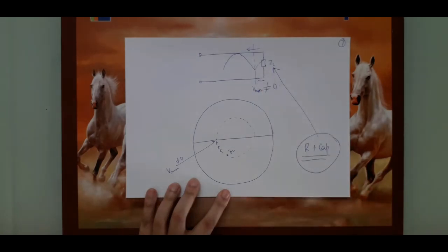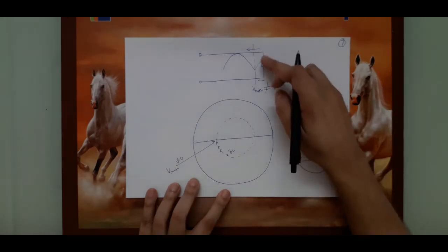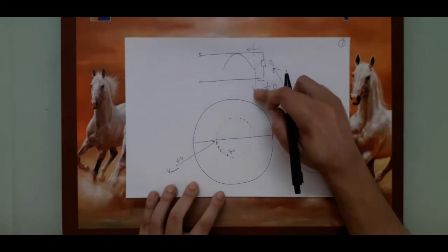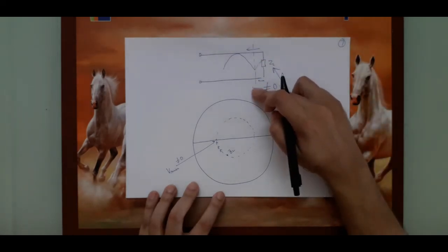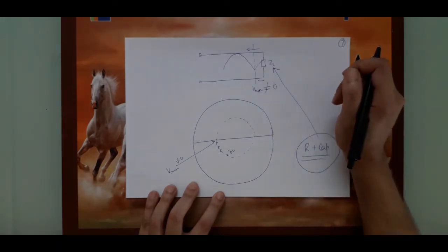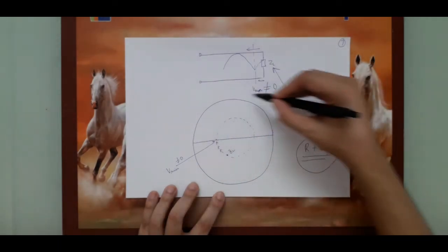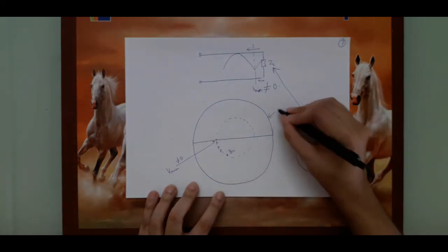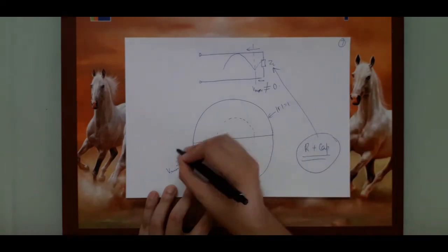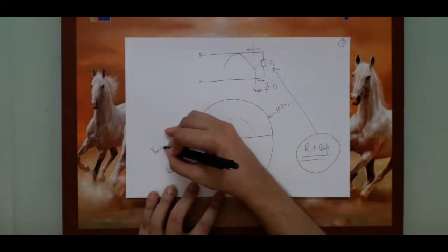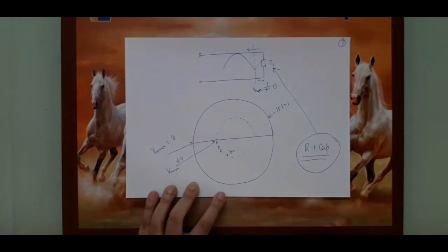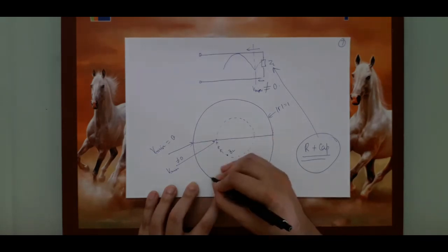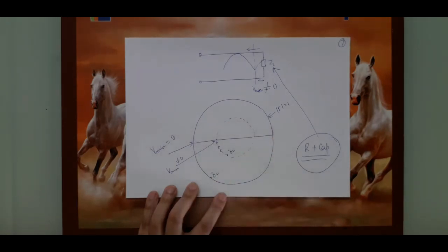Now, what would have happened if I started from some non-zero voltage, but the minimum I am encountering next would be a 0? In that case, our VSWR circle would coincide with the outer periphery of the Smith chart, or the gamma equal to 1 circle. In that case, our voltage minima would have been here. So that means the load would be somewhere on the lower periphery of the Smith chart. So in that case, it would have been purely capacitive.